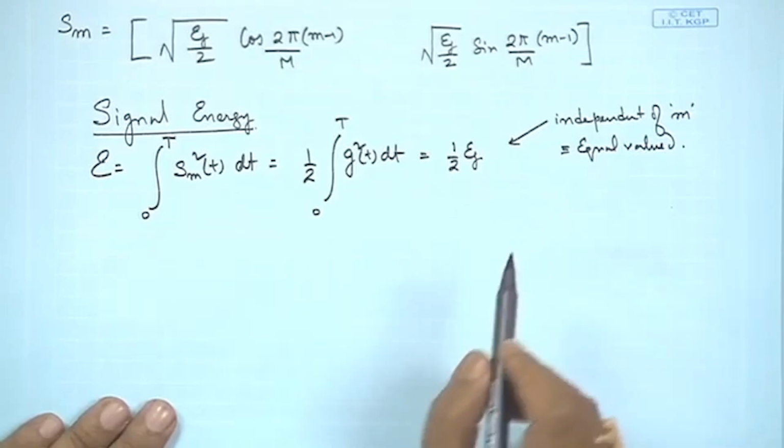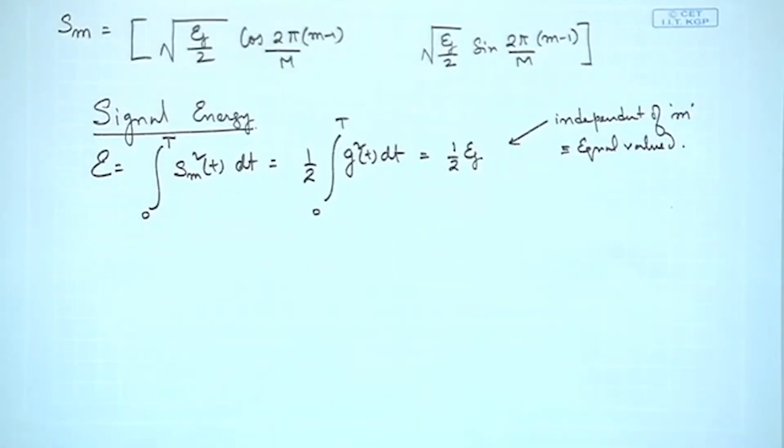The other important thing to note is that since the amplitude is constant, it is a constant modulus, you can say. That means the amplitude is not fluctuating. So, whatever advantage you had for angle modulation or phase modulation, you are going to get similar advantages here also. The only difference is that there you take a continuum set of angles, all possible angles between 0 to 2 pi, but here you have only fixed angles to select from. So, you have quantized, that is the major difference.